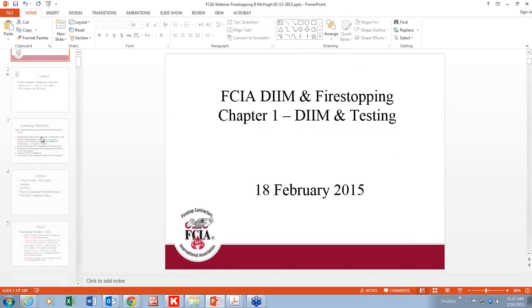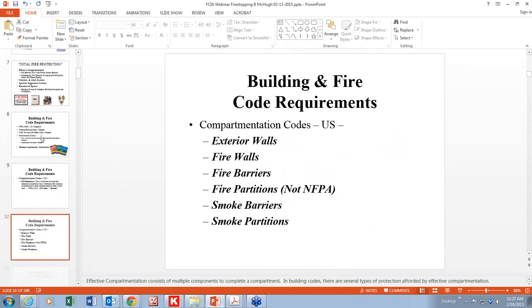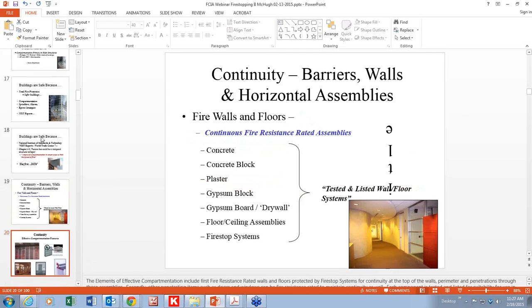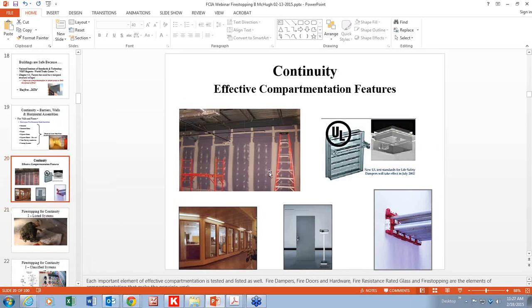We know that. See if I can bring up the picture of the fire resistance rated wall. I know I got a drywall assembly. So here's a fire resistance rated wall assembly. The best thing to do is to go back to the ASTM E119 assembly or the UL263 assembly in the U400 series and look and see what it says for patching that wall. The Gypsum Association also has a dissertation on patching wall assemblies.